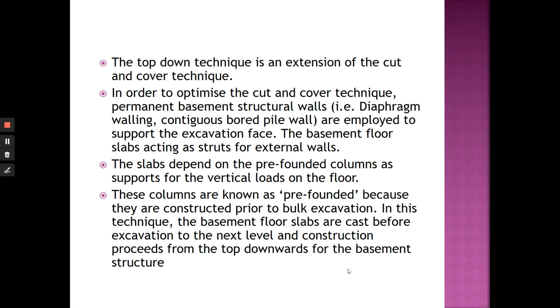The top-down technique is an extension of the cut and cover technique, as I explained. In order to optimize the cut and cover technique, permanent basement structure wall, like I said just now, they don't use soldier pile or sheet pile because it needs to be permanent. Permanent basement structure wall, diaphragm wall, or contiguous bored pile, or even secant pile. Okay, the basement floor slabs acting as struts for external walls. I have explained and I've showed you.